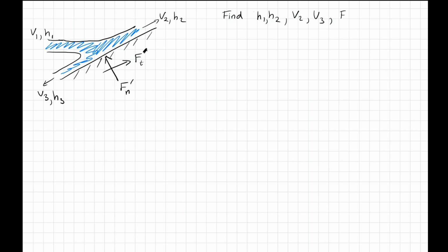But in fact, because I'm going to say that this is a frictionless flow, so let me finish writing this out. So if this is a frictionless 2D flow, and in fact I assume that it's a steady flow, so if the jet has been impinging for a long time, this will come to a steady state, then in fact there is no way for force to be transmitted in the transverse direction to the plate, because the way that a fluid does that physically is using shear stress.